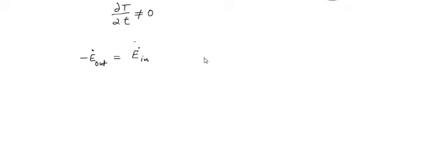Okay, so if you consider the internal temperature Ti here, we know that Ti is greater than T infinity, where T infinity is the ambient temperature or the temperature of the liquid. Until Ti becomes equal to T infinity, there will be a change in temperature. The temperature goes on decreasing, which means there will definitely be a heat transfer from inside to the outside surroundings.